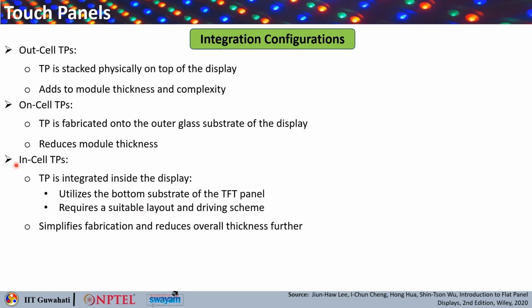There is another one called in cell touch panel. It is integrated inside the display. It uses the bottom substrate of the TFT, thin film transistor panel, that is used to drive your display, but it requires a suitable layout and driving scheme. This simplifies the fabrication and reduces the overall thickness further.